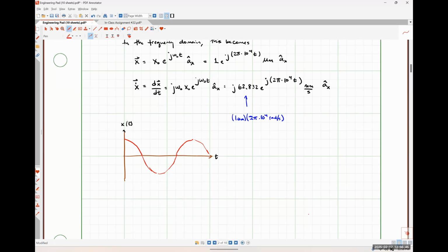So on and so forth. Well, at this point right here, when my displacement is at its peak, what would my velocity be? Well, it has to be zero because essentially my oscillation is changing directions, right? So when I'm at the peak value of my sinusoidal function, my velocity has to be zero because I'm changing my displacement from increasing to decreasing, right? So that inflection point means that my velocity had to be zero.